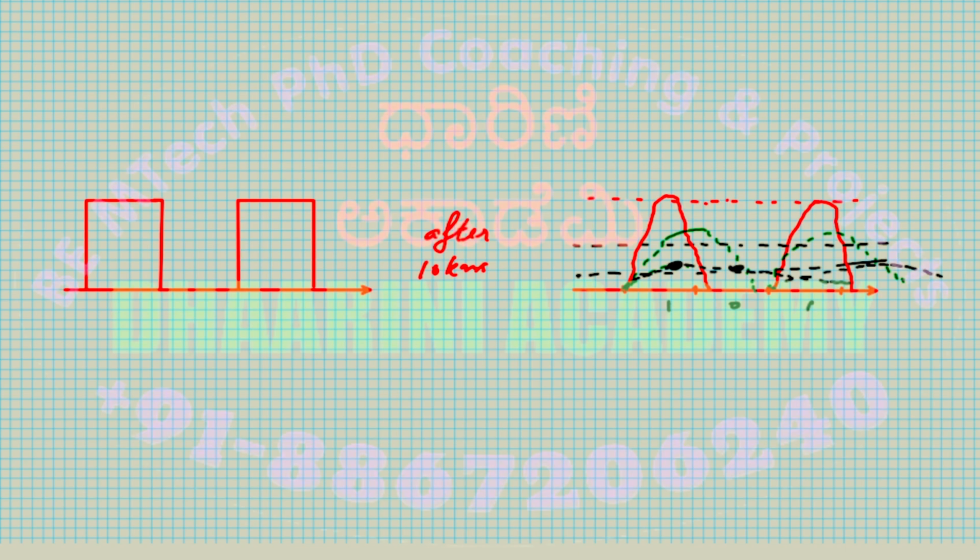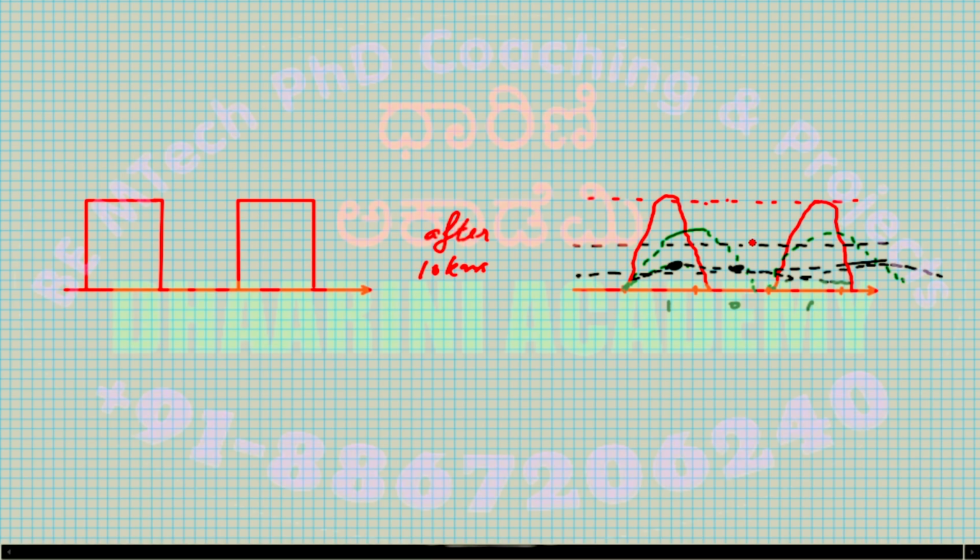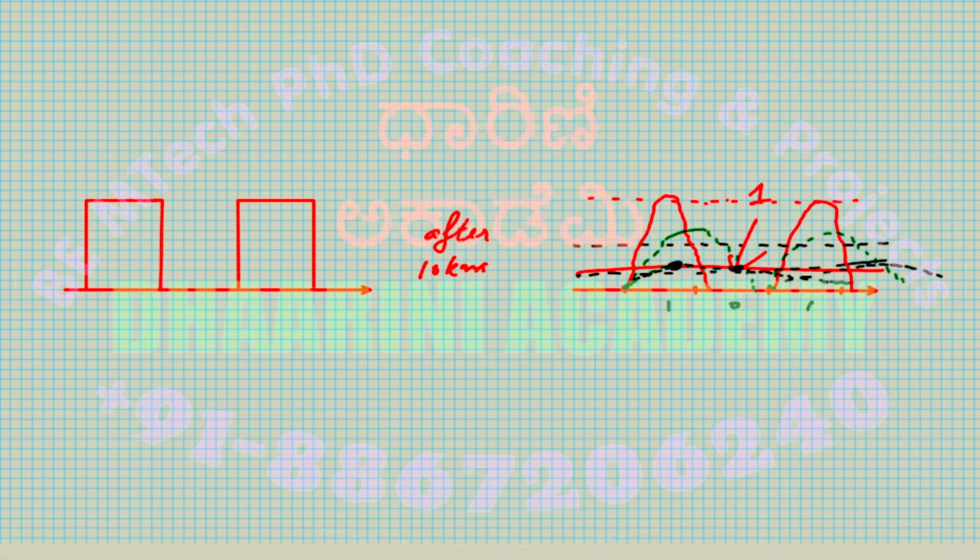So this concept, one symbol entering into the energy space of the other symbol, because your second symbol was 0, but the 0 was detected as 1 here. You see, if the lowest threshold is selected, this point will be a 1 on the receiver side, right? Which is a mistake, error, right? So you see, one symbol entering into the space of the other is called inter-symbol interference.